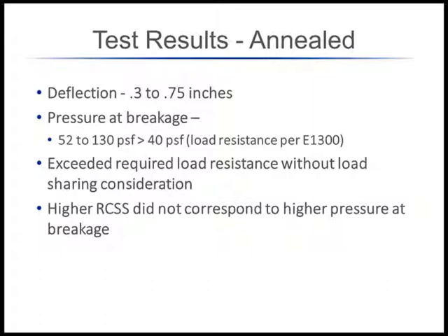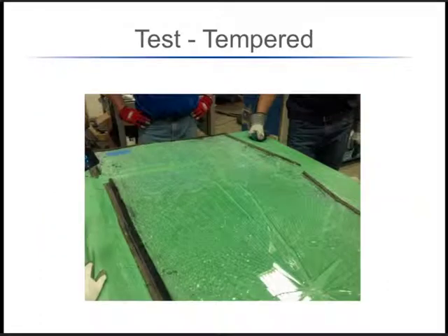So we moved on to testing the tempered glass, and because these were the inboard lights, they didn't have the surface damage like the outboard lights did. But like we talked about earlier, they're still considered in-service glass with some weathered characteristics. So we felt that as long as we had those tempered lights, we should test them to see where they came out. You can see this is one we actually laid down on a table just to see the breakage pattern.